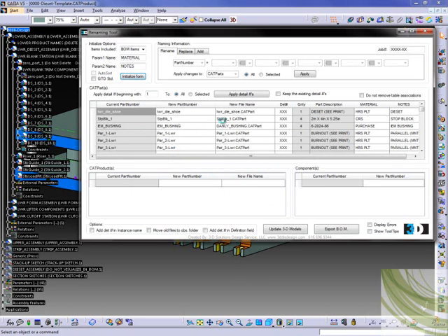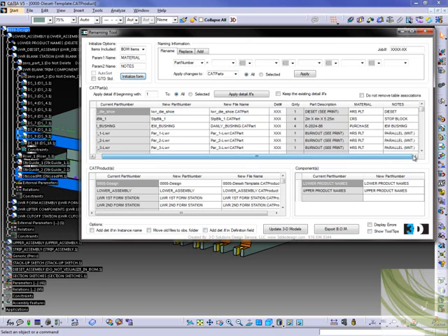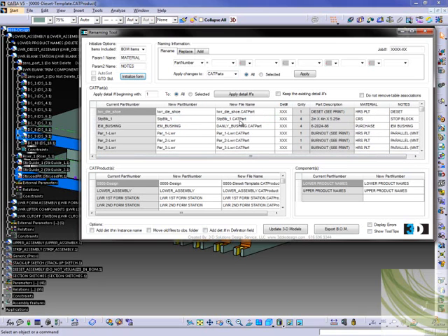You can see it pulls in all the information on the blocks: existing part number, new file name, detail number, quantity, description, material, and notes. These are customizable too. We can add as much as we need to this, but we'll just run through the general form right now. Once these are loaded in here, first thing we would want to do is apply our detail numbers to our blocks. If we have existing detail numbers, we can keep those by selecting the check boxes.